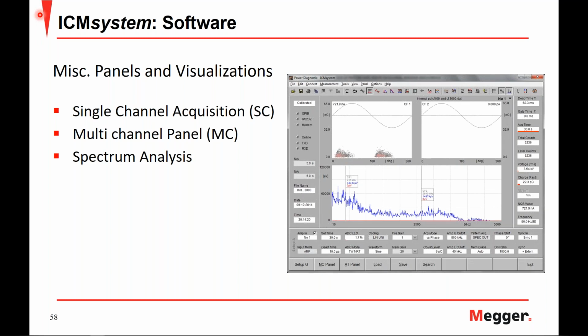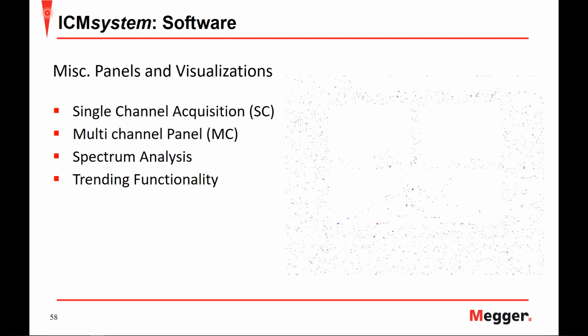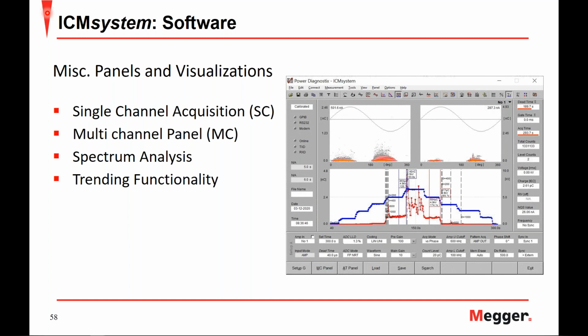Next, you have your spectrum analysis, which we covered before, and offers the benefit of being able to choose the optimal bandpass filter for your measurement, or measuring bandpass. Next, you have the trending functionality that allows for trending of the step voltage while the partial discharge measurement is taking place. The trending file can be reopened, and you can use the phase resolved partial discharge patterns for your reporting, or you can use that trending file to generate a short video for later use.